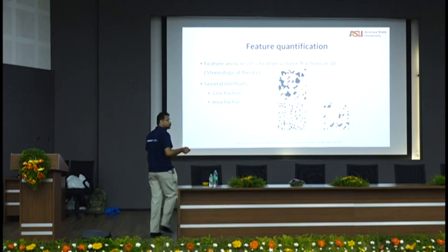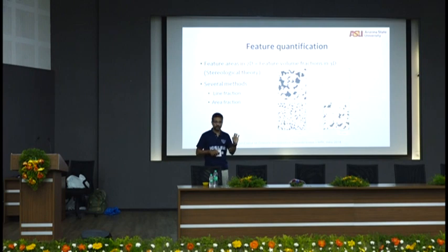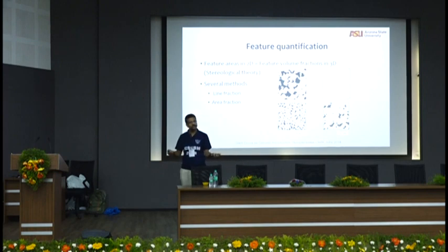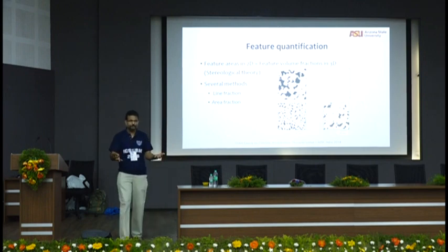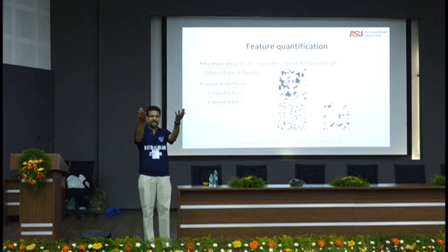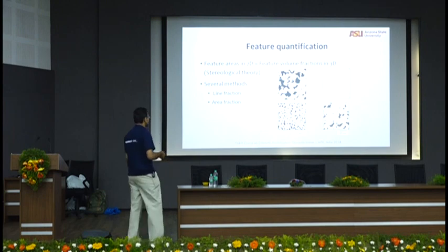Now many of these tools can actually draw a line around it, calculate how many pixels are inside, and then divide the number of pixels inside by the total number of pixels. That also will give you the area fraction. Area fraction of pores in 2D, if I have enough of them in the z direction, can I average them in some statistical manner to find out the 3D representation, and that will be my porosity. So this is one simple way of doing it in image analysis.